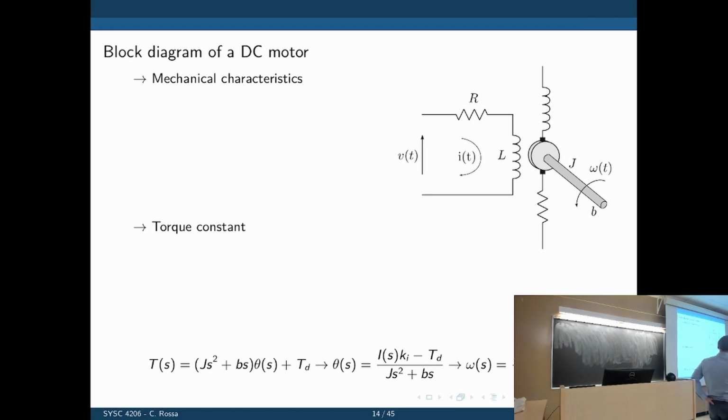The mechanical part is basically an inertia, J, and it has friction in contact with the stator of the motor. That friction coefficient is B. So for the rotational part, we can say that all torques apply to the motor. The sum of all torques is equal to, well, if it's a static system, it would be 0. J, the moment of inertia, times its acceleration, which is the derivative of the speed. All right. Let's write this in Laplace domain to make it more fancy. Omega times S.